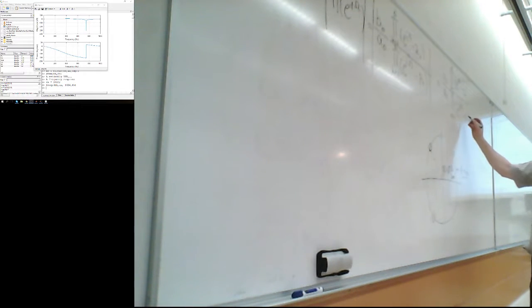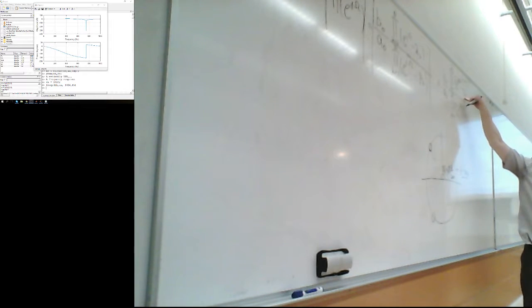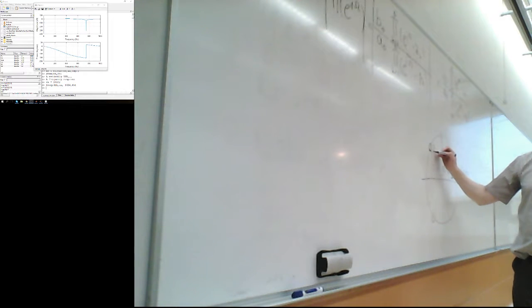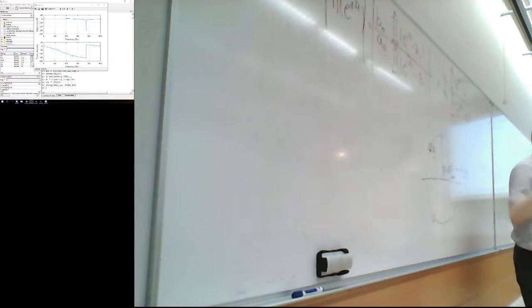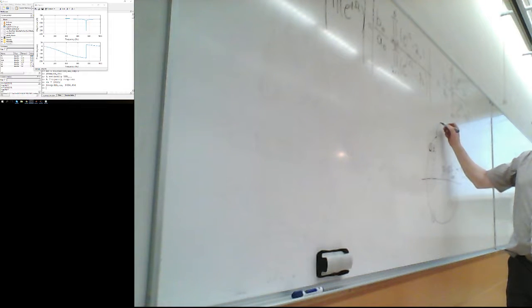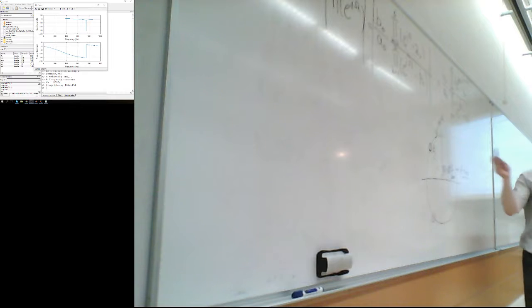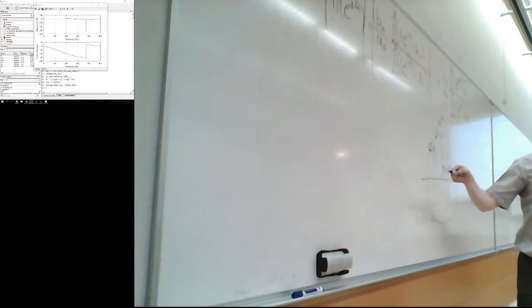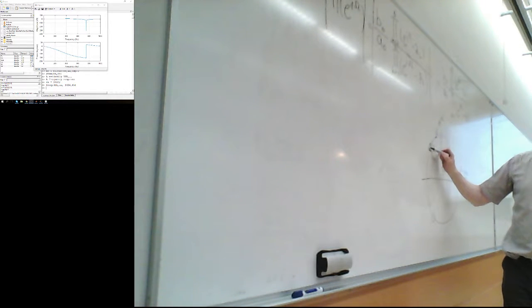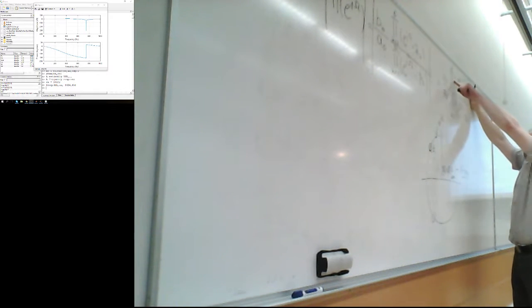So on that frequency, we actually hit the unit circle, so the distance between that one and the zero is 0. Remember we are talking about the point e to j omega here, and that's moving on the unit circle. When it hits that point, this distance becomes 0.